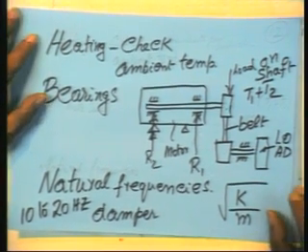One can estimate those natural frequencies of various segments of the transmission system and see whether the forcing frequency can be kept away, or if you have to pass through the natural frequency to attain speed, you have to make sure there are dampers, otherwise vibration will set in, resonance will set in. So these are some of the things which one should examine as he uses these motors and the associated systems.